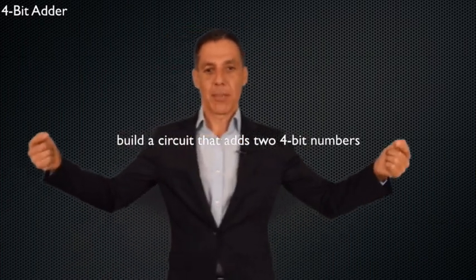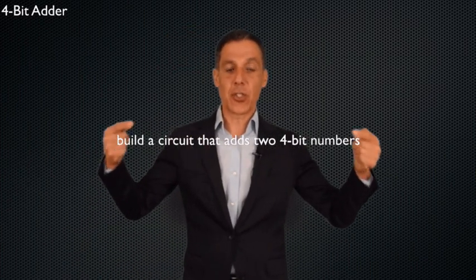We do binary arithmetic, or addition. And obviously, we're going to use the 1-bit adder that we just built, because we know that n-bit addition is just a series of these 1-bit additions, so we're going to build them. We're going to build this in a smart way. All right, so please build for me a circuit that adds two 4-bit numbers.